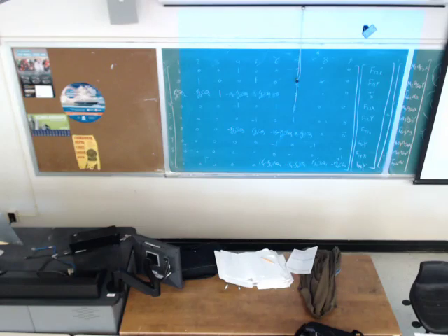You have done displacement, velocity, and acceleration analysis in homework 4, 7, and 8, which is due today. We assume that the input link is rotating at a constant speed, meaning alpha 2 is 0. We would like to do it for the open mode, the first mode, when I'm saying open mode, meaning that all 3 links are on the same side. We would like to do the force analysis for all input angles from 0 to 360 in a step length of 5 degrees.